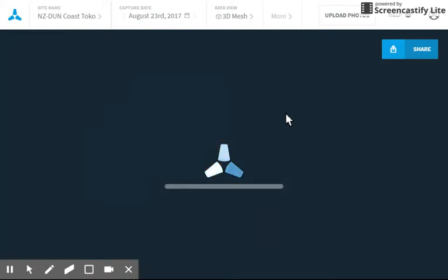Whilst it's loading, the drone is programmed to take an automatic grid flight within an area that is specified by the operator from the controller using an iPad. The photography is taken every 2 or 3 seconds and has an overlap in the region of 70 to 90% in both directions, lateral and leading on the camera. This high overlap allows us to identify the same points in multiple photographs to allow us to create a 3D arrangement.